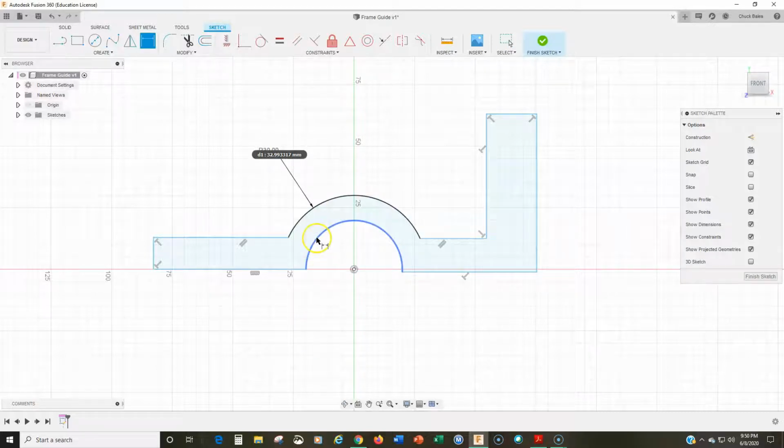Okay, and the inner radius is actually not given as a radius. It's given as a diameter, 38.1 to 37.97 to 38.10. That's a tolerance dimension, so we can draw it within any of those ranges.